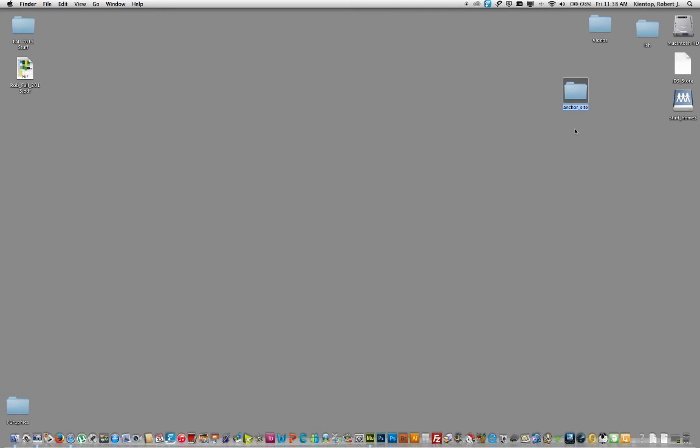If I highlight the name, you notice that none of the characters in that name are actually uppercase. They're all lowercase. I'm not even using a space. When you work on projects that are aiming toward the web, we want to use web-safe naming conventions. And one of the rules is to not use uppercase characters. Also, spaces can cause troubles on a lot of older browsers.